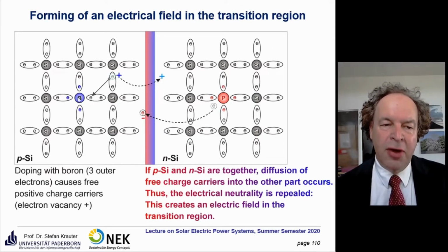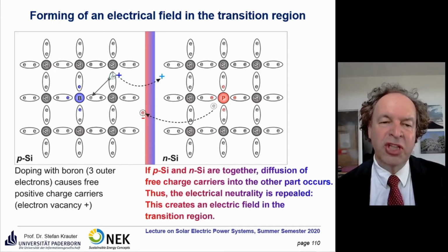There's also the other way around, so-called p-silicon. There you dope with a boron atom. This boron atom only has 3 outer electrons. That means in order to complete the links in the tetrahedral formation to the neighboring silicon atoms, there's always a missing electron. What do you do if you miss something? You can borrow it from a neighbor. That's the case here. So he is missing something, so now he got it from a neighbor, but then the neighbor is missing something, and therefore it's called a missing electron or hole, like a virtual positive charge you have here.